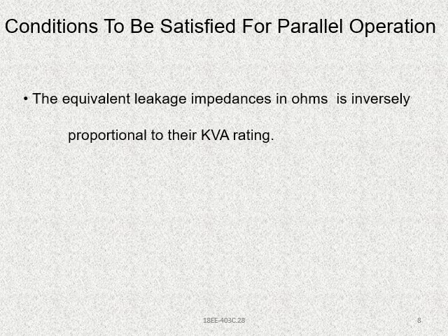Next, conditions to satisfy for parallel operations. The equivalent leakage impedance in ohms is inversely proportional to the kVA rating. Same thing, this is the fifth point.